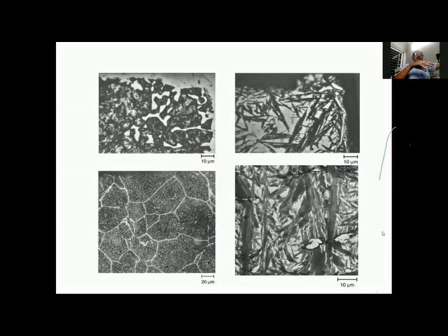again the effect of excess carbon, grossly excessive compared to the optimum carbon of eutectoid, or 0.8%. So you will find in the upper left a very heavy carbide, although to some extent they are disjointed. They are not fully connected.